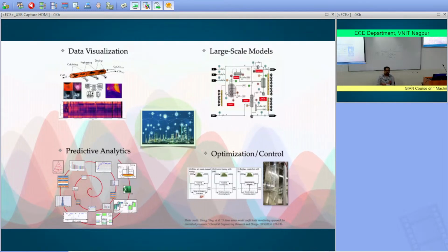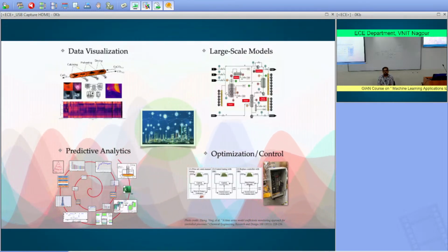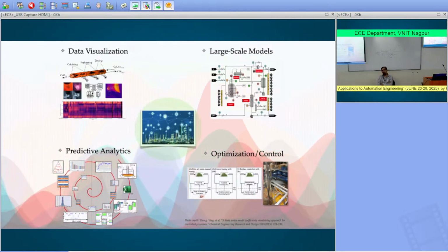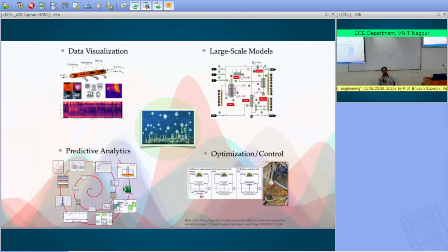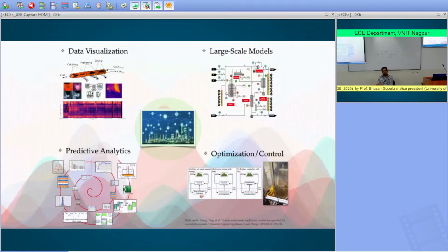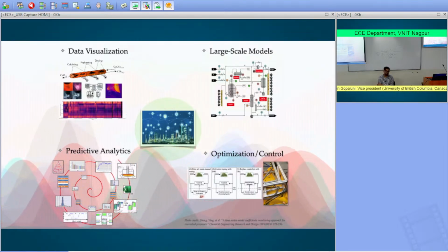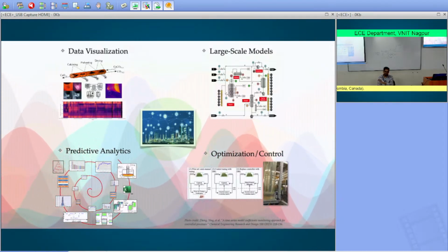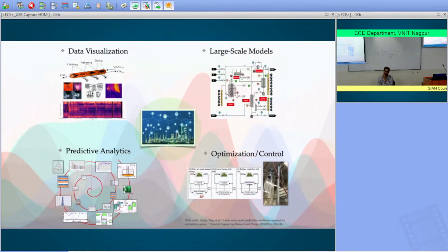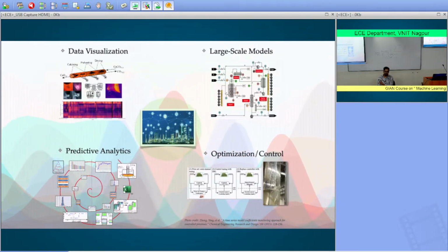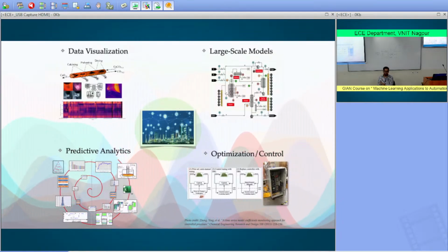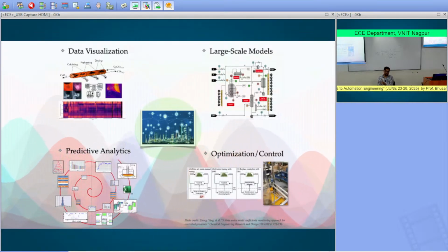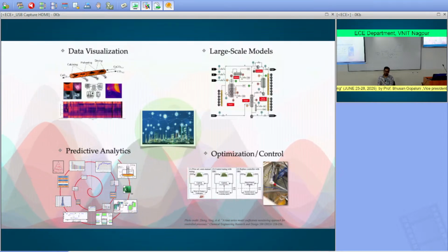So when you want to design a PID loop, you build a model, and then there are some standard tuning methods you can use to extract the controller parameters, right? But the model itself is not explicitly in the PID loop. There are certain versions, IMC, for instance, internal model control. You can embed the model explicitly. But the PID controller itself, there's no explicit model, right? So you can think of reinforcement learning in a similar way. There is no explicit model in it. The agent has certain parameters, you're fixing those, and that's pretty much it. You're not explicitly building a model.